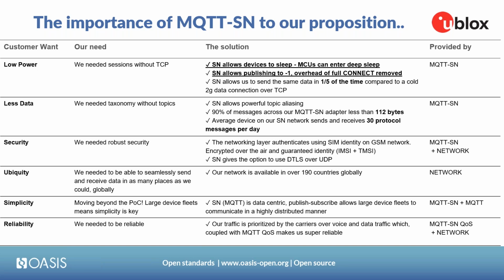Many of our customers employ the sleep cycle to preserve their battery life. They're able to make huge power savings by sending the device into deep sleep while having sleeping sessions on the broker, maintaining their state. They can choose to wake up and receive their messages or simply publish to quality of service -1 directly from a sleeping session itself. And this fire and forget metaphor is simple and massively effective.